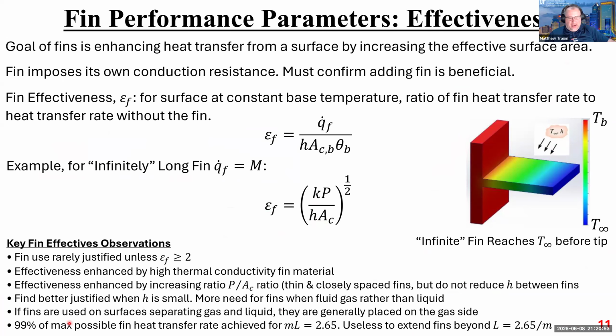Okay. And then I say here 99% of maximum possible fin heat transfer rate is achieved for the product of mL equals 2.65.